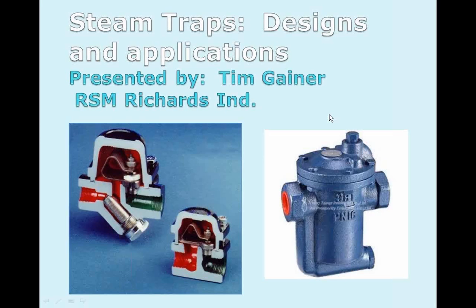It's also useful for telling if you have leakage, because like I mentioned on the disc trap, they're loud and you might hear that sound as it opens and closes, but just because it's closed doesn't mean it's not leaking. So ultrasonic will let you detect flow that's going through there even when it's closed. Ultrasonic can be used on a modulating trap, and what you want to see on the outlet is some adjustment of that flow. So you'll see that the ultrasonic level's changing.